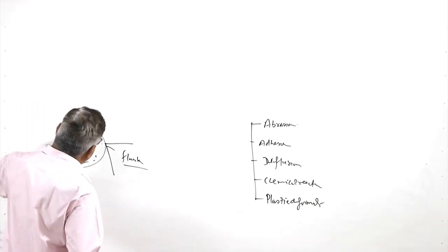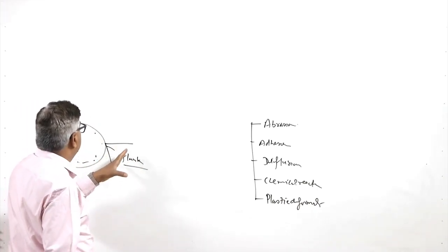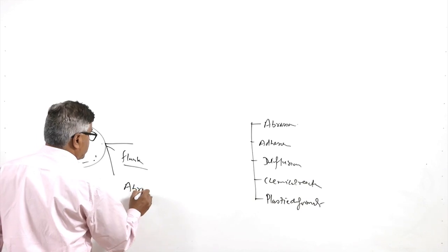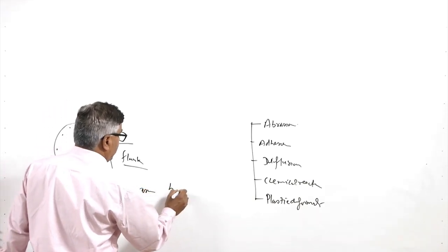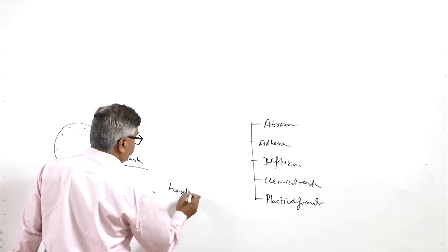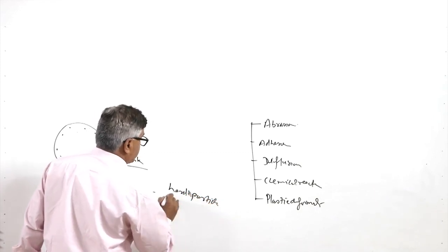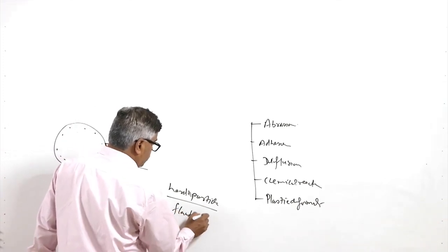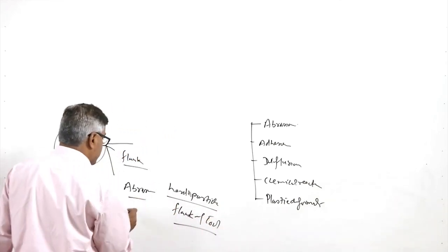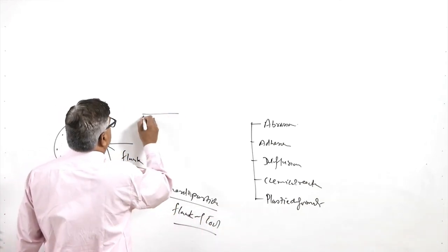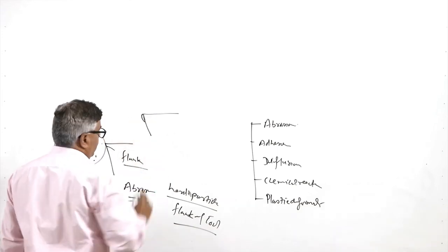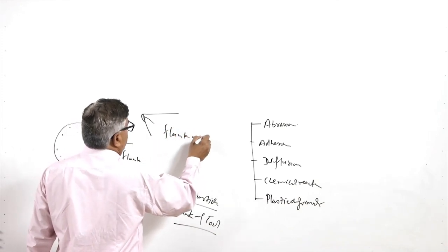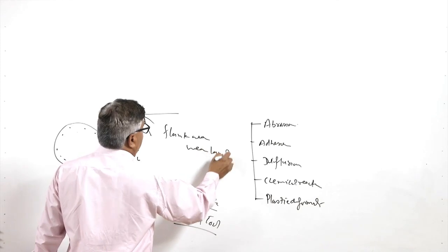These hard particles frequently come in contact with the tool flank, and this causes abrasion. It causes wear in the flank in the form of flank wear or the wear land.